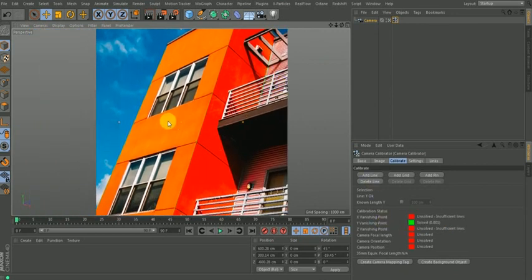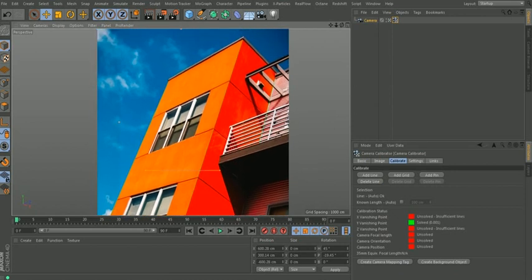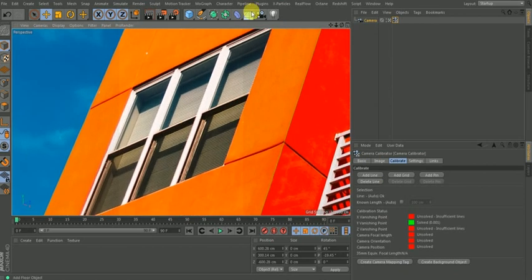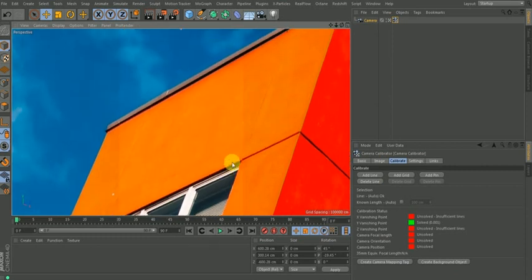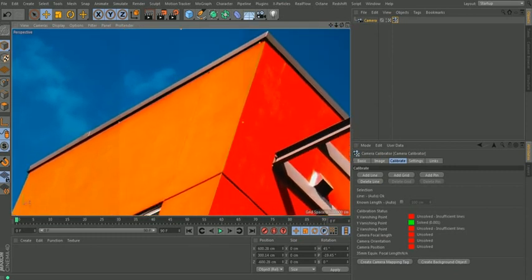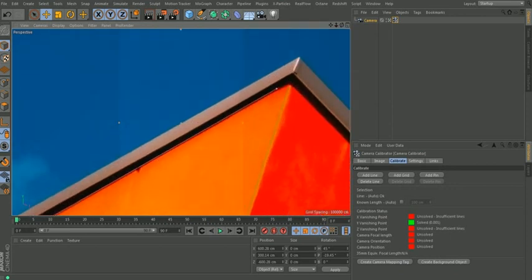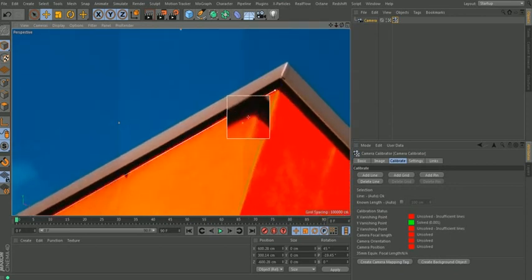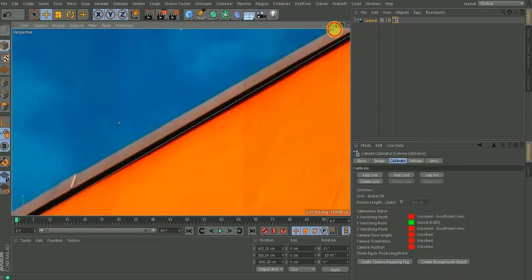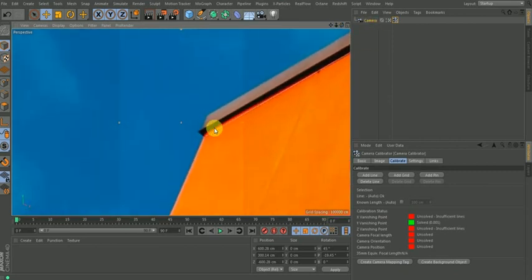So the next thing is I need to solve for my x. So I'm going to create a new line, then start solving for this. So I'm going to bring this x here. This is where I want my x-axis to be. So I'm going to zoom into this place, pan down. Don't forget, you hold down your shift and control, then use your left mouse and your right mouse to pan and to zoom. So this is okay. Let me just use this point, then this will be here.